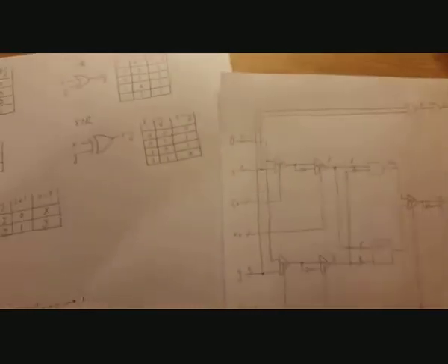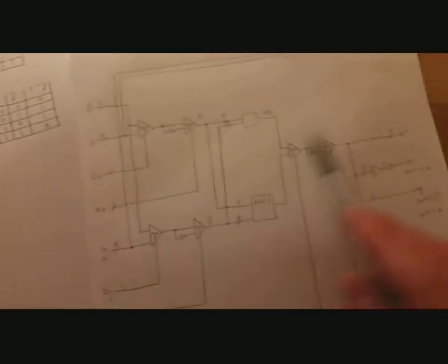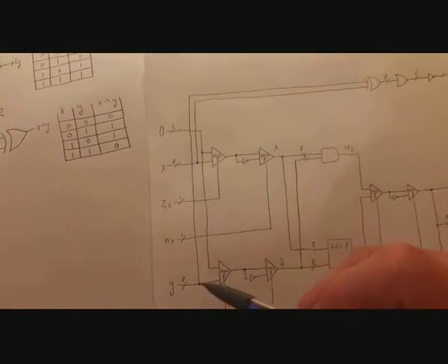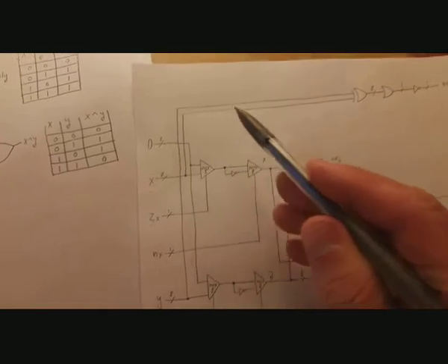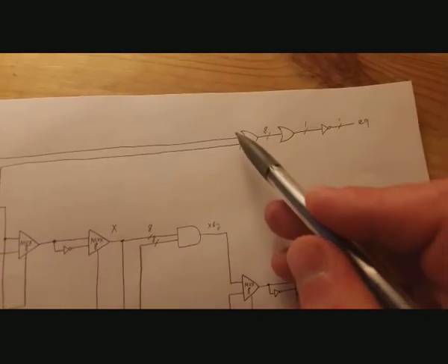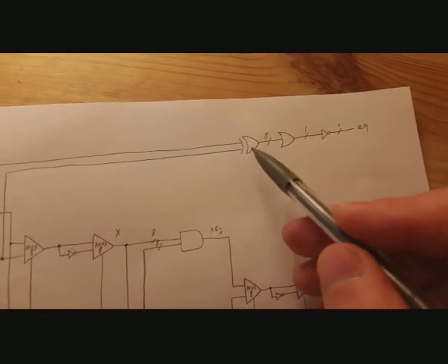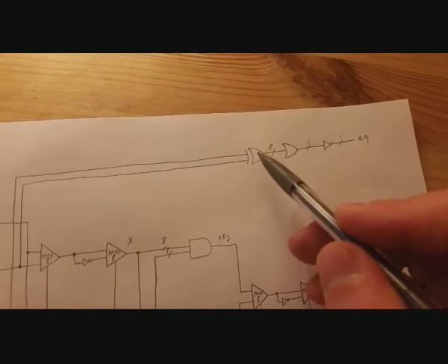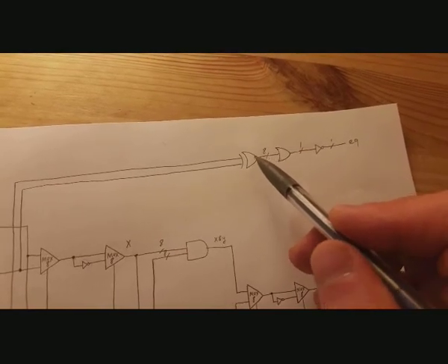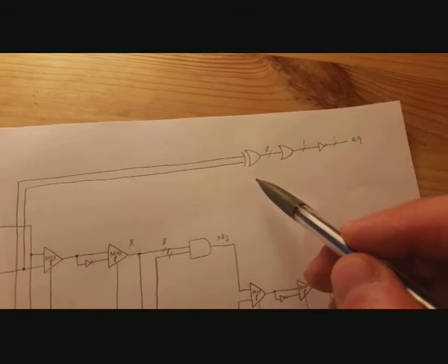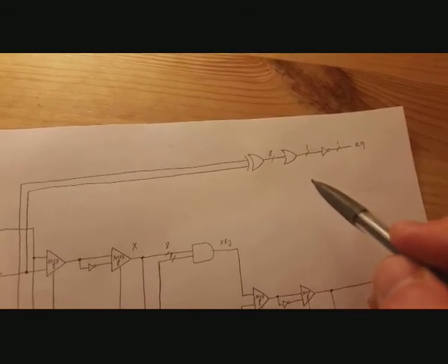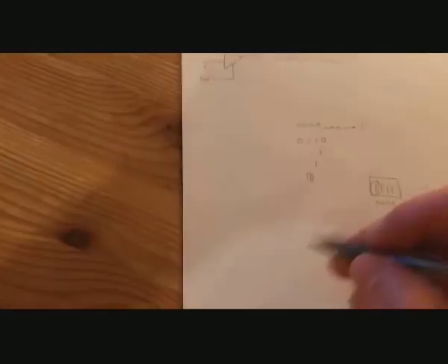So what I want to do is, in parallel to all of this, take X and Y, branch those up, and send them all off into an XOR gate. I want to XOR all of them: take X and Y, XOR them together, then take the result of that and OR each bit of those together. So I'll show what I mean here.